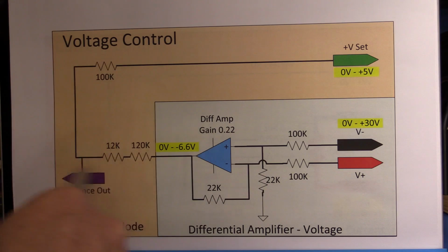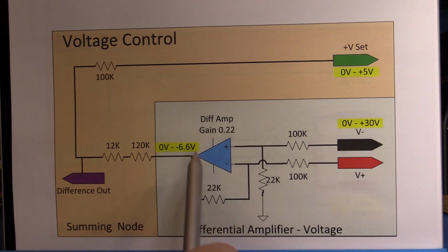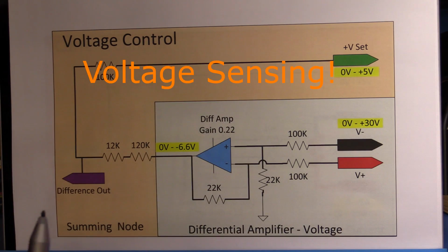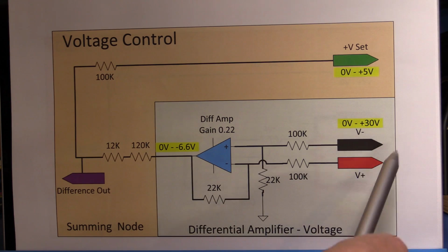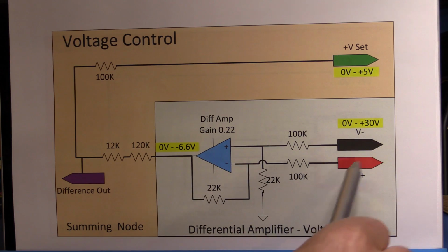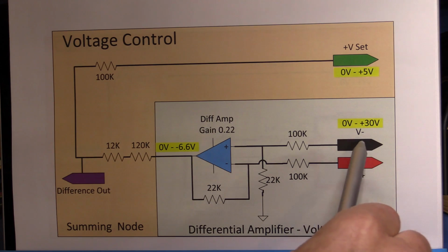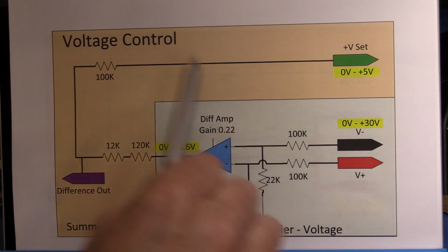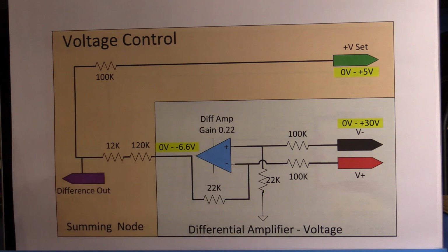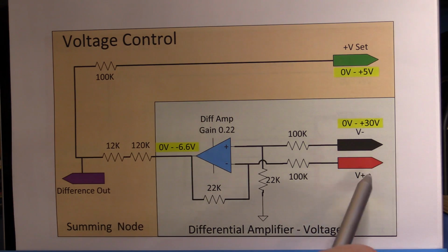All right, now let's ignore this piece of circuitry over here for the moment, and let's now look at the current sensing area over here. So what I have is the standard op amp, and we've looked at this before. I've got the sense inputs, so we're using differential, so we've got 2 of them. One goes to the positive rail of the power supply and one goes to the 0 volt rail of the power supply. Now these are the output pins, remember, not across the smoothing capacitors of the power supply. It's the actual output after any control system has been put in play.